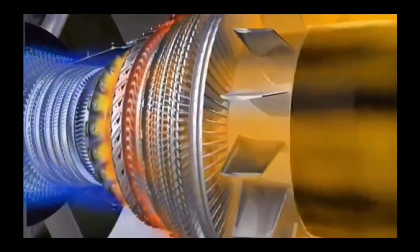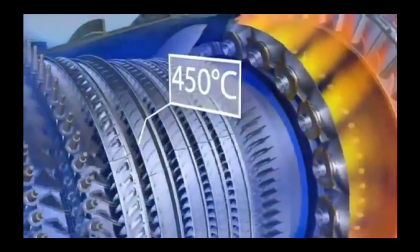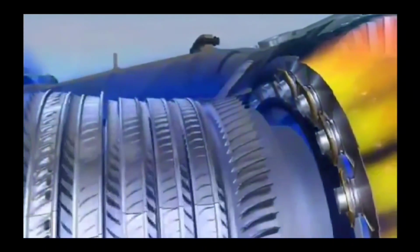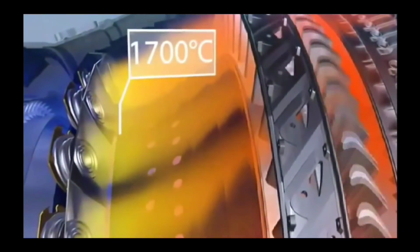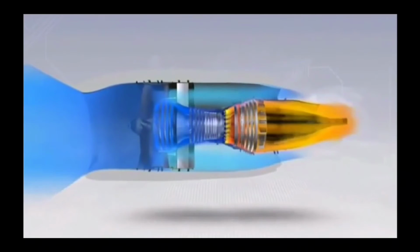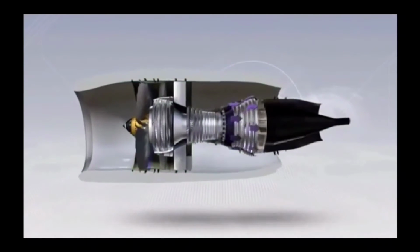through the exhaust assembly. The air is compressed in the low and high pressure compressors, and its temperature can reach 450 degrees Celsius, after which it enters the combustor, where fuel is injected and ignited. Burning the mixture of fuel and air brings the temperature up to 1700 degrees Celsius. Finally, the accumulated energy is extracted in the 5 turbine stages immediately after the combustion section.